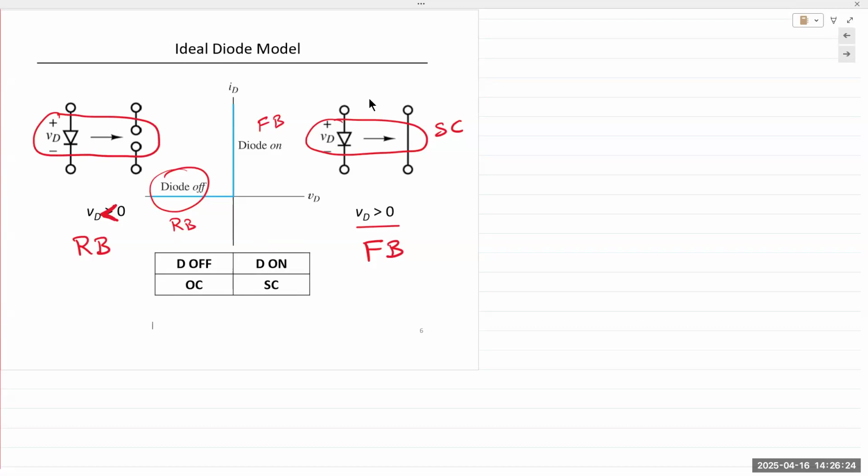For instance, think back to lab 1. Lab 1, we had the 555 timer chip operating as an astable multivibrator and an oscillator. So its output is a rectangular, a square wave. It's on, then it's off, it's on, then it's off, right? Then we feed this output into a diode circuit through a capacitor.